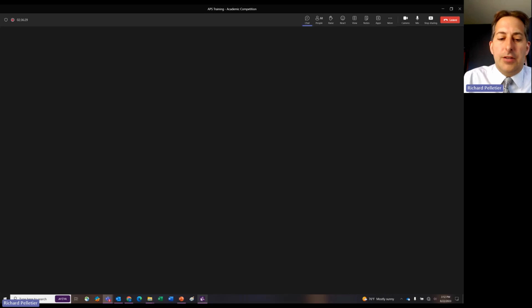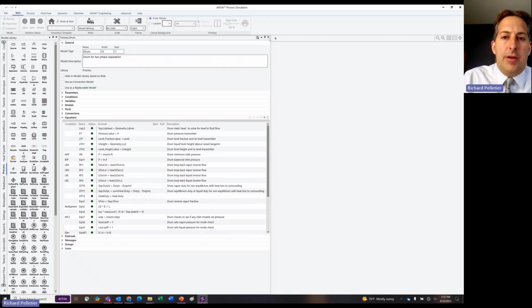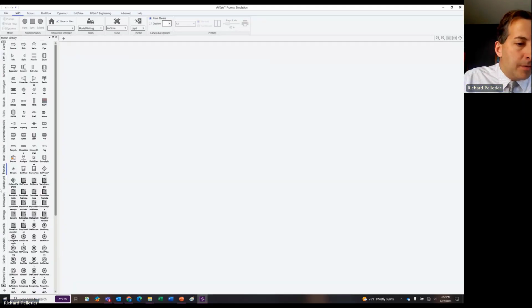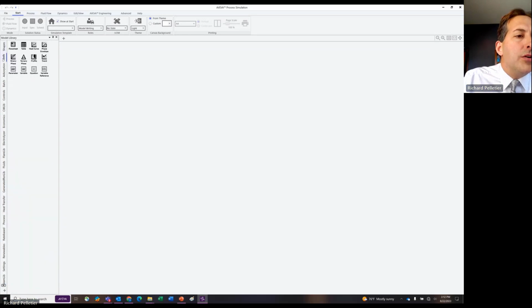And then there's also, we don't talk about it in this training, but if you go to the tools menu up at the top, there are other thermo-related outputting capabilities that you have here that can link to the fluid, such as BVLE calculations, binary curves, and ternary curves that you can create, right?